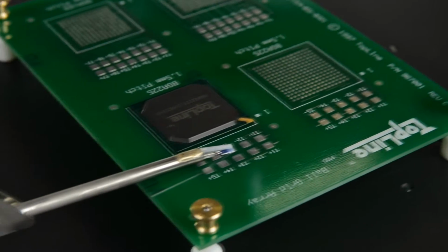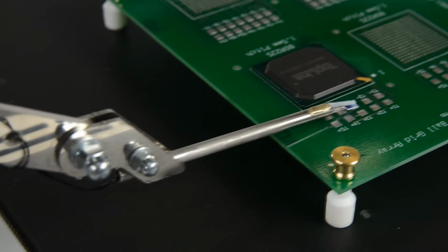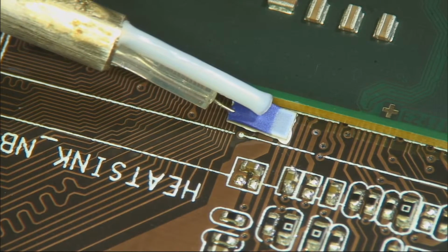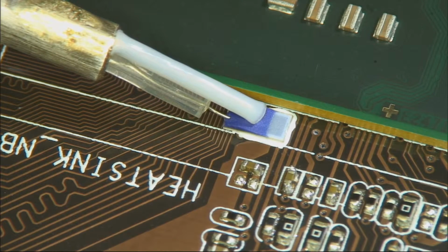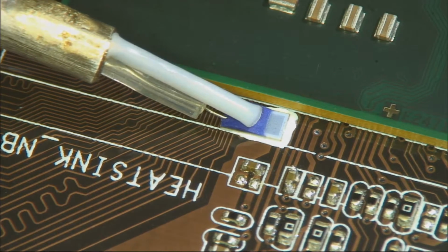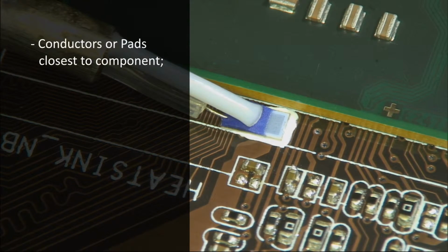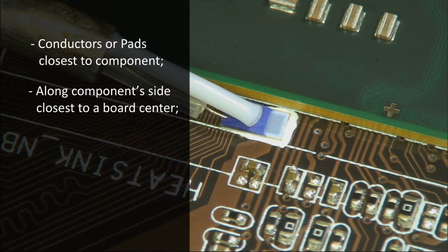Correct positioning of the control sensor on the board is the most critical operation, which guarantees temperature readout precision. Please follow our simple recommendations. Install the sensor on conductor traces coming from the component, or on a metal field situated as close as possible to the component. The sensor is to be placed as close as possible to the component side which is most distant from the board edge. The sensor has to be aligned to the board with its whole bottom surface.